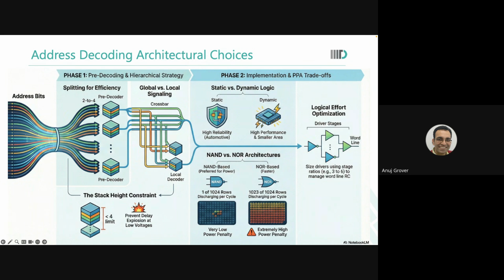So we try to keep the stack within 4. What this may mean is that we are decoding the addresses in multiple stages. Already we were talking about pre-decoding and post-decoding, but if the stack height has to be maintained to be low, then there may be an additional stage that could happen either at pre-decoding stage or at post-decoding level. Are you with me?